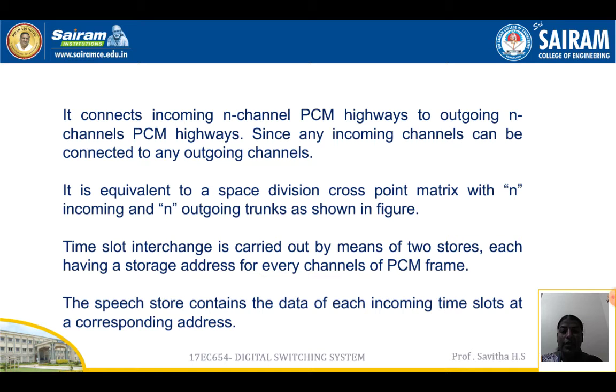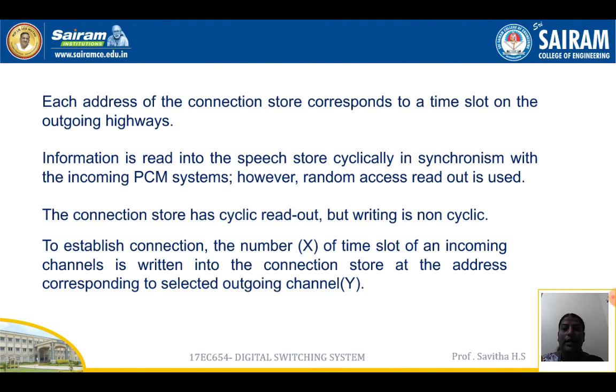The speech store contains the data of each incoming time slot at the corresponding address. Each address of the connection store corresponds to a time slot on the outgoing highway. Information is read into the speech store cyclically in synchronism with the incoming PCM system. However, a random access readout is used. The connection store has cyclic readout, but writing is non-cyclic. To establish a connection, the number x of the time slot of an incoming channel is written into the connection store at the address corresponding to the selected outgoing channel y.